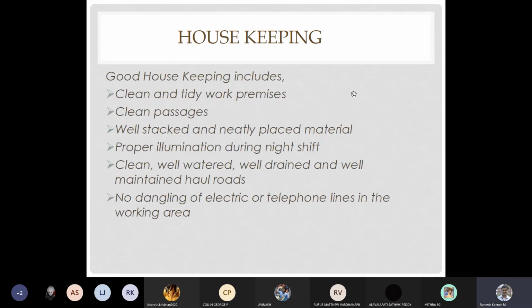Then a very important thing, housekeeping, as we call it in terms of maintaining the necessary working condition. So that's what I put under the term called housekeeping. But this should not be taken as only the cleaning stuff, but also filling any patches or potholes or something like that. These are the people who generally check daily. So when a crane collapses, the first question they're going to ask is who has been maintaining this particular facility, and then they look step by step into the crane operators, and then the loads and other calibration of the cranes and so on. Right, so that's very important.